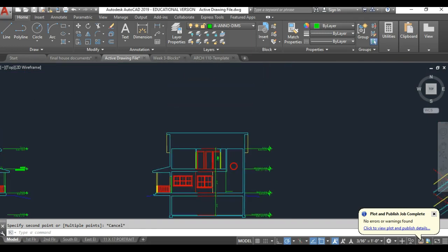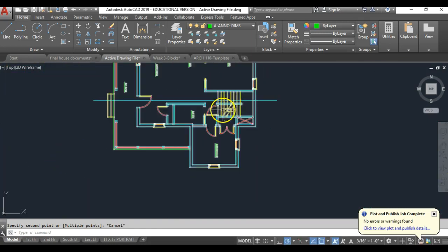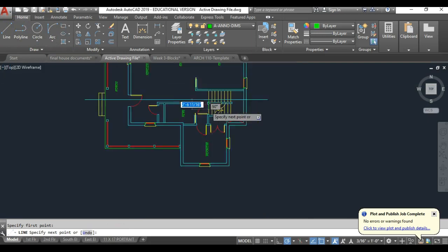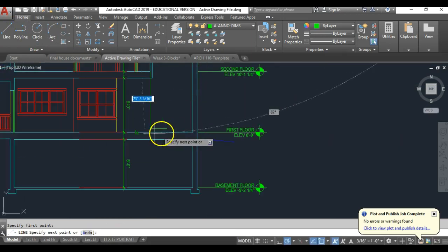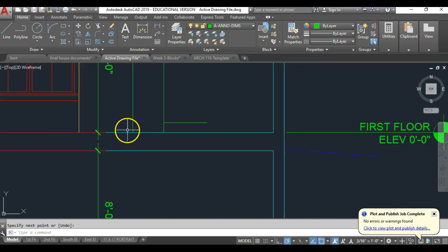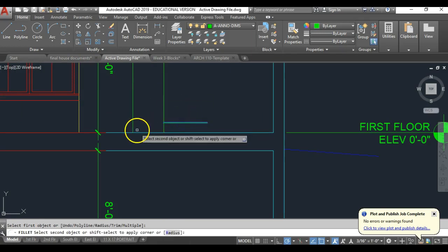Now there's a number of ways of doing the treads and the risers, but really what I can do is say, okay, well here's the section cut. Here's the first one that's going to come off the ground from that point here. So I'm just going to take this line and draw it straight down, which is going to be way over here when I use perpendicular snap, but I know it's going to be this high, so I can actually run fillet, which is going to be F,